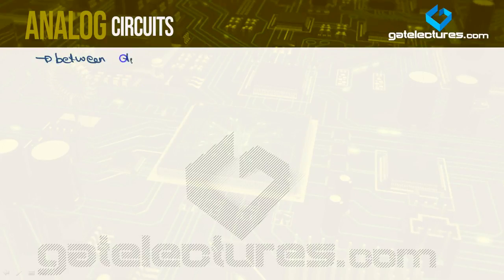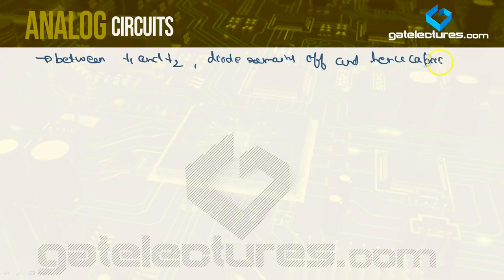Between T1 and T2 the diode remains off, so no charge flows through the diode, and hence the capacitor supplies all the charge to RL. There is only one discharging path, that is through resistance RL.